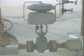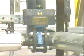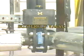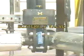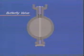All the control valves we've covered so far have been linear motion valves. Now it's time to look at some of the common rotary motion valves. The butterfly valve is one of the most common rotary motion control valves. Inside, these valves have a rotating vane that provides the valve closure. These valves offer simplicity and low cost, as well as good flow control characteristics.